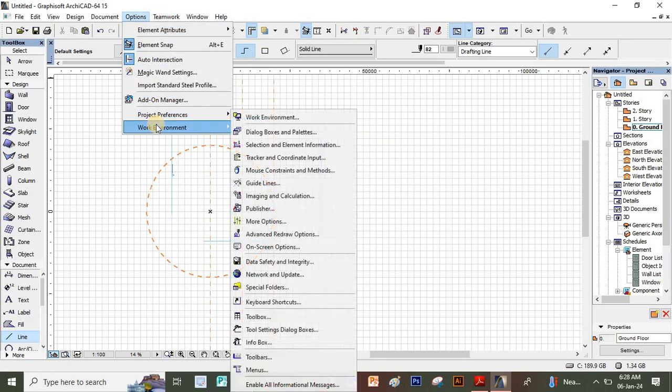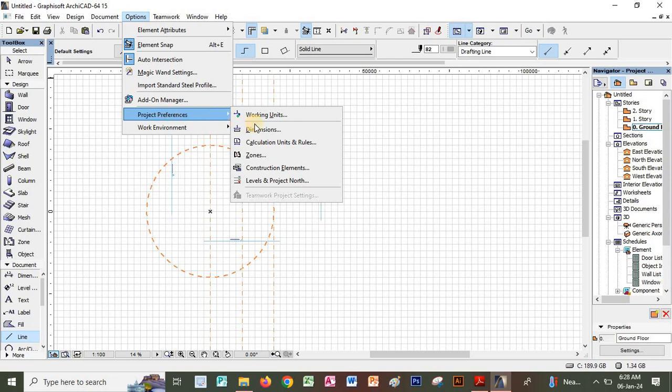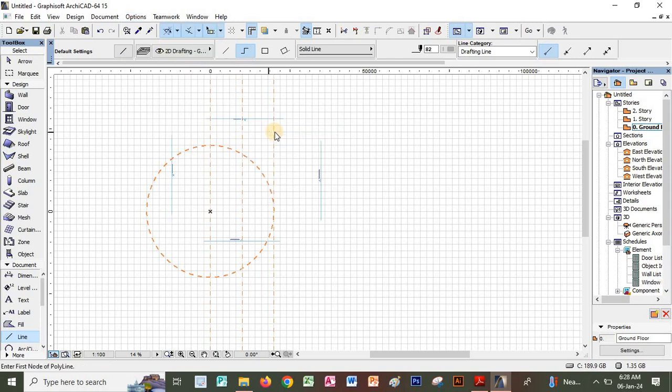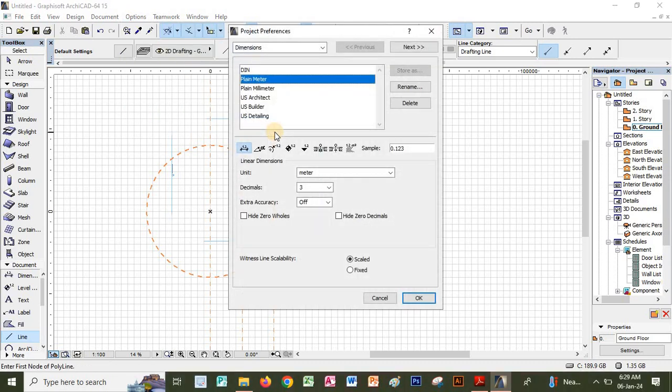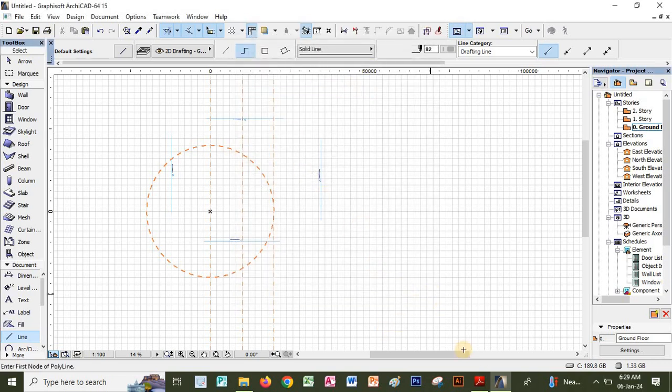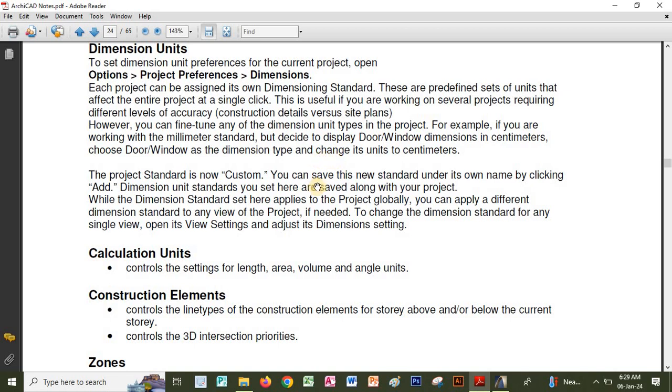If it is something else like dimensions, if your units that you are working with are millimeters, then also make sure the dimensions that are set are the same, so that you are working with the same dimensions as the units set.